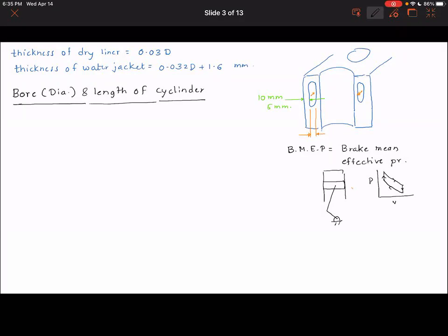You would observe in this cycle, the pressure is continuously changing. So in other words, the pressure inside the cylinder, this is the pressure, is continuously changing depending upon whether it's a suction stroke, compression stroke, a power stroke or expansion stroke, and exhaust stroke. So what we do is we try to find out sort of an average pressure across the entire cycle.